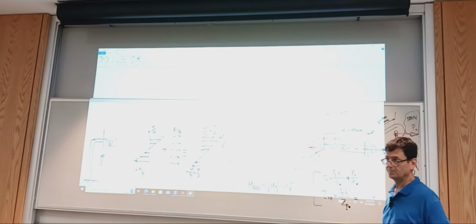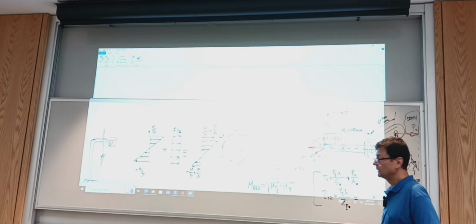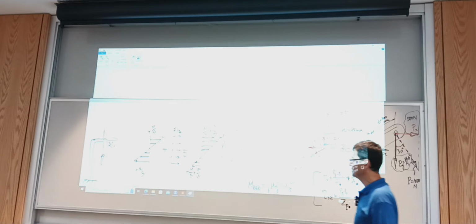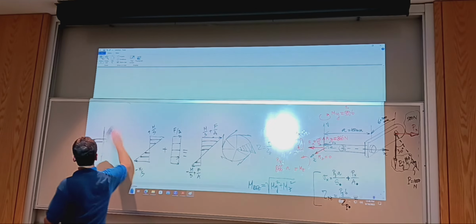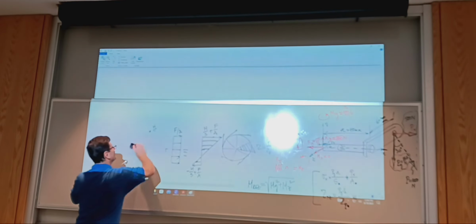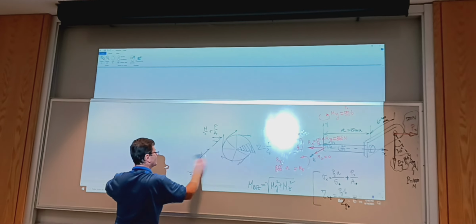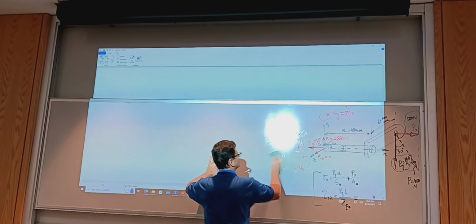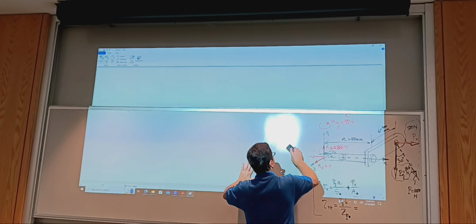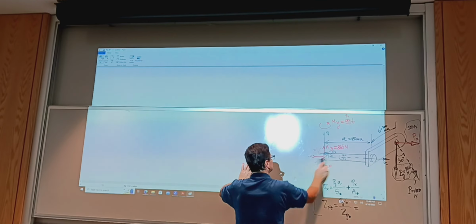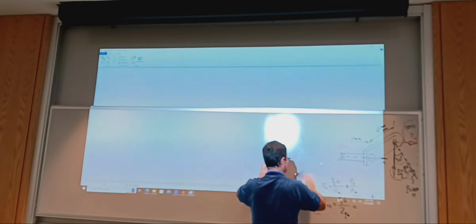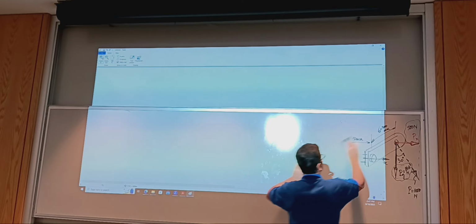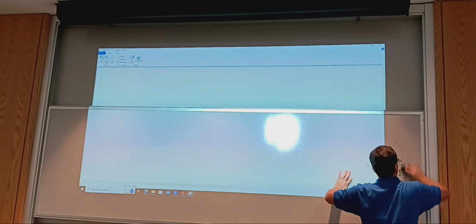It's just forming the circle. But as you do problems on your own, draw the Mohr circles by hand, and then you can go to the spreadsheet. There are also online apps that do Mohr circles, but I think they don't always match the sign convention in the book. Some just calculate the principal stresses using equations only, without drawing the Mohr circle. We'll do it in just a little.